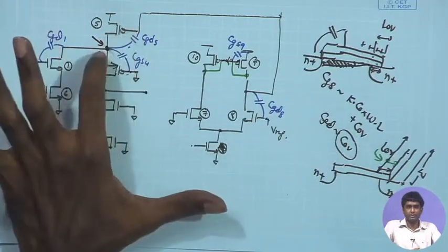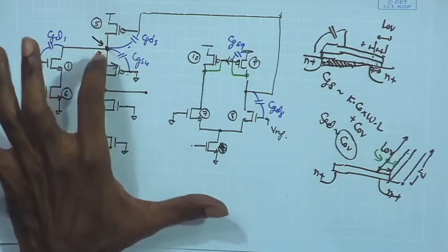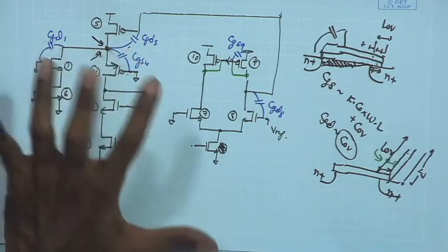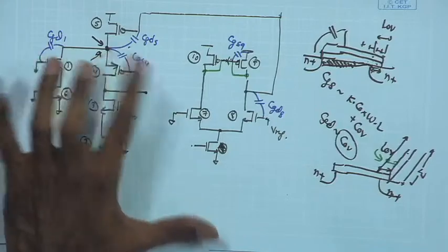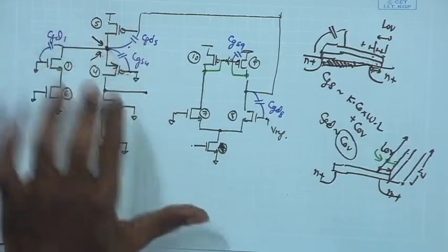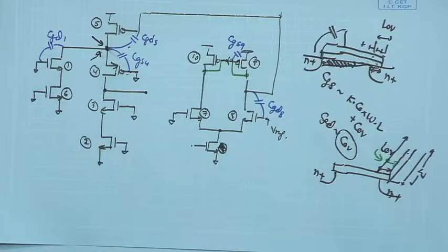So, it serves to have a better idea of the device structure, so that we can think about which device is contributing to the dominant and non-dominant pole over here, so that we can judiciously choose the sizing of the other devices while satisfying multiple criteria, say the compensation and the noise together.